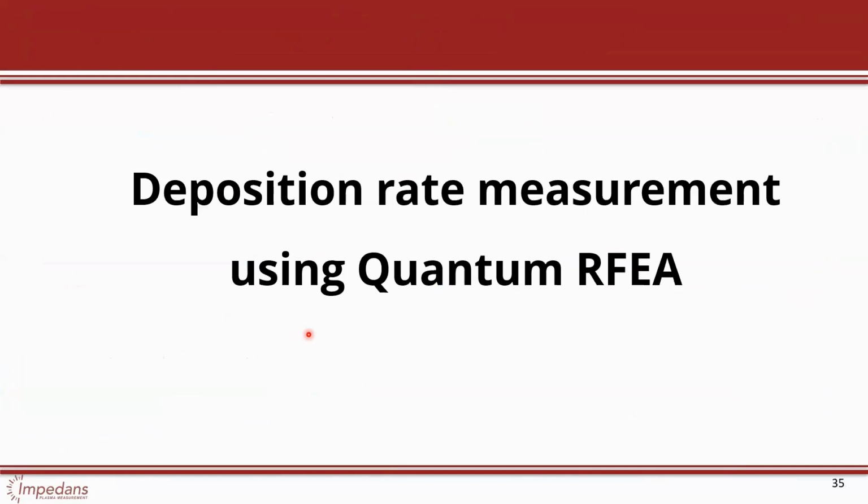Yeah. So the next thing is, okay, you can measure the distribution versus time and the flux versus time. What about the deposition rates and the ion neutral ratios? They're another important factor, especially for HiPIMS. If your goal is to maximize the ionization fraction, you have to optimize that. How many microseconds do I want to have the plasma on? How long do I want to have the kick on? These are the things you have to optimize. Do you want it on for 25, 30, 35 microseconds, which will give you the maximum ionization fraction without secondary effects causing an issue?